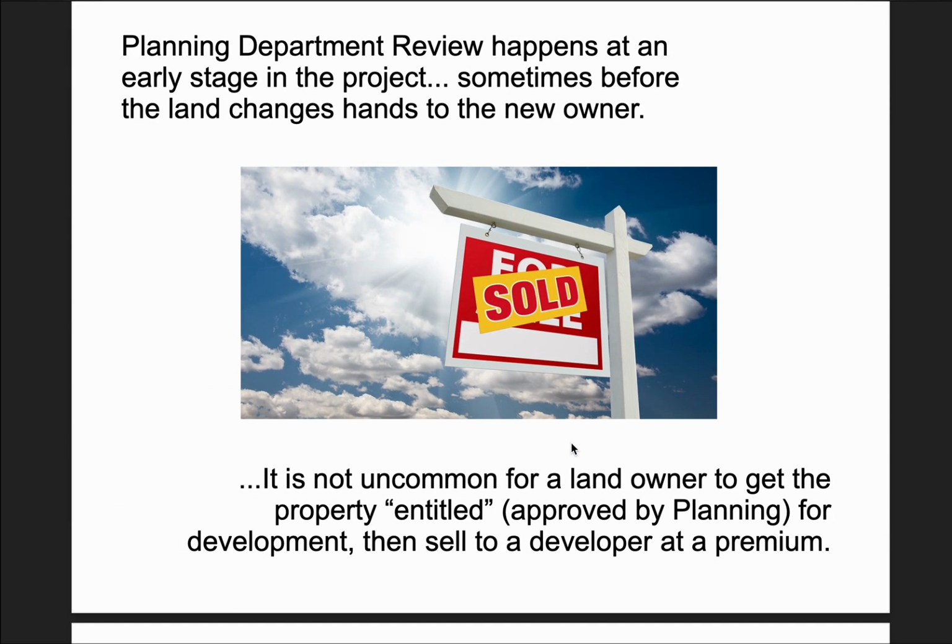So the planning department's job is to review the portion at the early stage of the project, which involves site plan and land use, and for big projects where there's actually no plan yet, where a developer will buy a big tract of land and would like to develop that for a subdivision, and would like to get approval from the planning department. This process is called entitlement, where the planning department approves this for a specific use like a subdivision and what the density is.